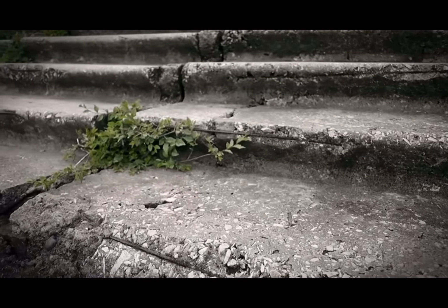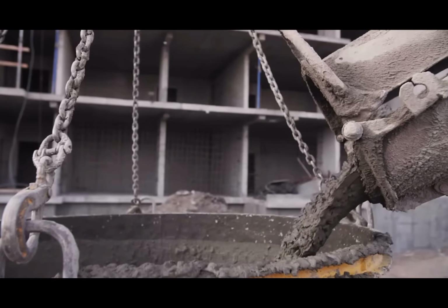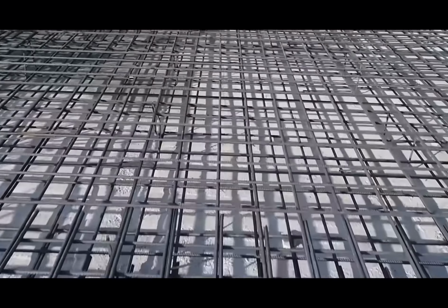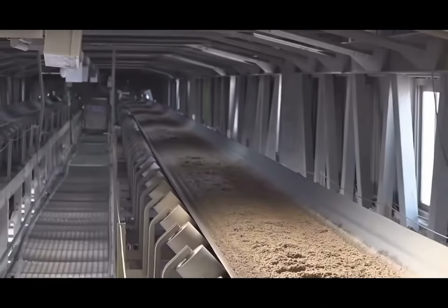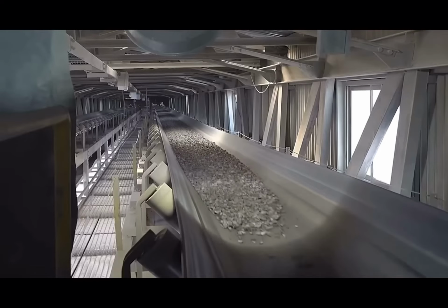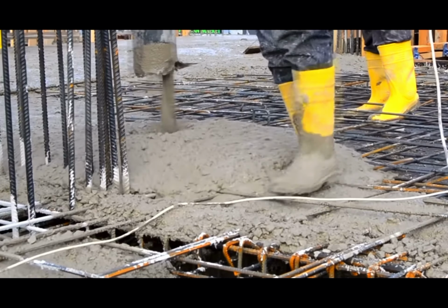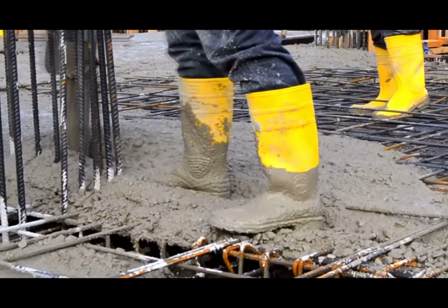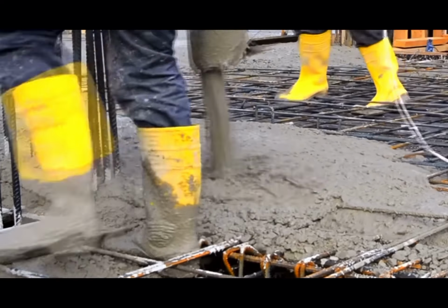Due to the fact that concrete cracks under tension, many chemical additives have been developed to increase the tensile strength of concrete. Concrete may also be strengthened by using fibers made of stainless steel, glass, and carbon. With the raw materials all there, concrete production can finally begin. The first step is to measure the proportions of cement, aggregate, admixtures, and water based on the desired strength and characteristics of the concrete. In fact, concrete mix design is an entirely different discipline dedicated to finding out the right proportions of raw materials in order to reach a target tensile strength.